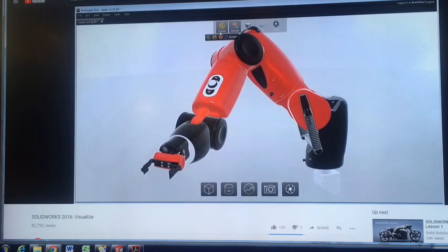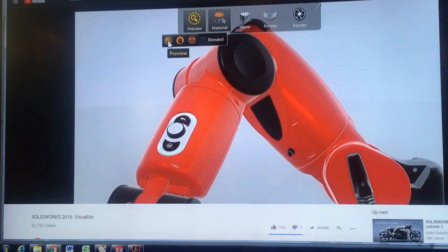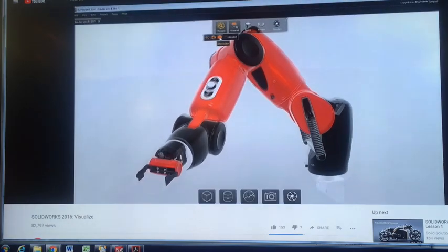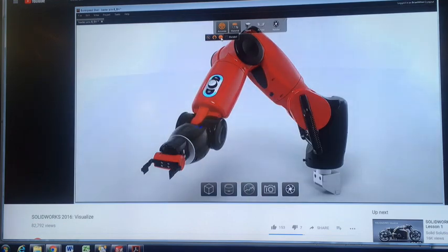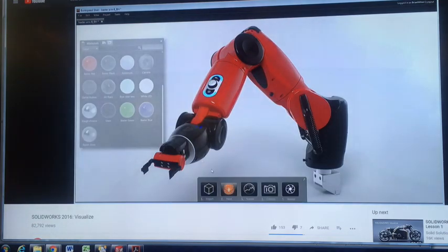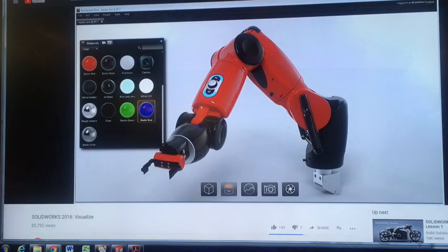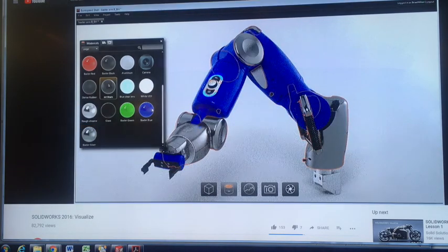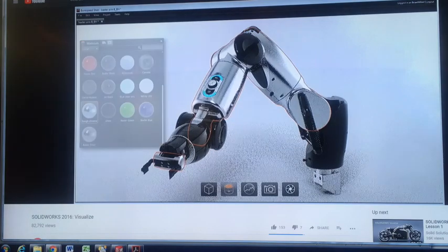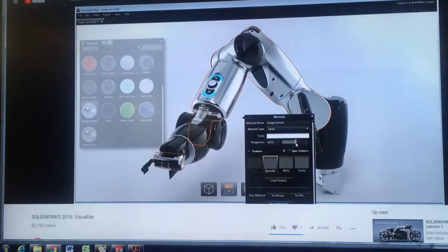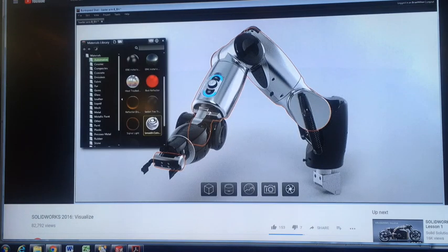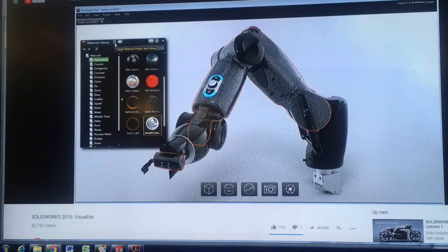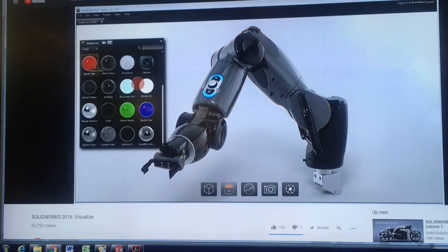amount of time. The viewport can be rendered using Preview for approximated rendering, Fast for high-performance ray tracing, and Accurate, which can utilize multiple GPUs for fully photographic ray tracing. In each mode, what you see in the viewport is what you get in the final image. Dragging materials from the library enables everyone to paint their model incredibly quickly and easily. Materials can also be customized by adjusting the surface finish, color, texture, and more. Additional materials can also be obtained from the online community, which contains loads of free, professionally made assets.